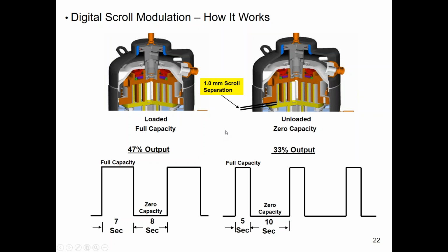Mark asks, why non-free draining on larger evaporator coil sizes? It's just the way the headers collect, the suction headers, some of them are non-free draining. The number of outlets or spigots, suction spigots into the header, just the whole construction of the coil.